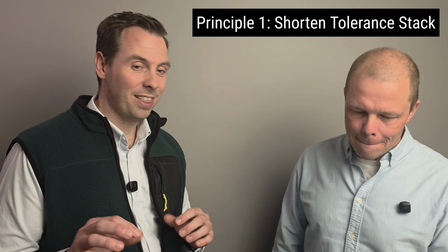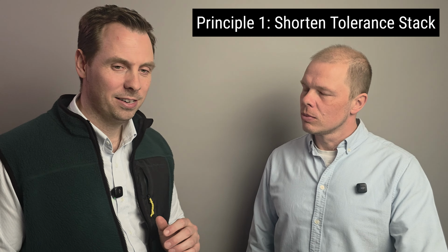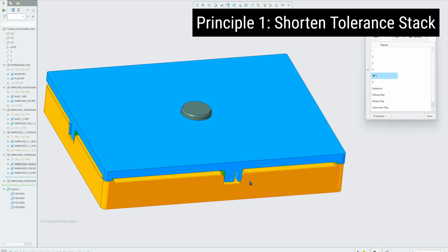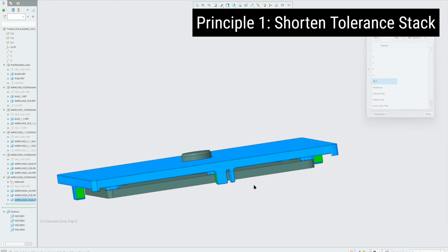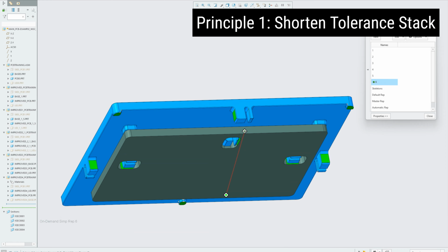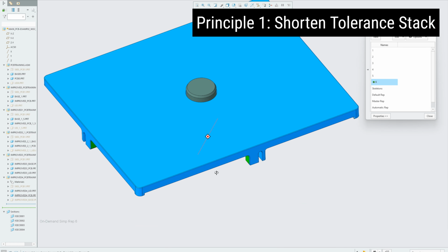There was also this principle number 1 where we could short circuit the tolerance stacks and say if we can eliminate any parts, let's do that. We're not allowed to apply this in this case. Would have made this video way too short. Exactly. So here you see that example where we hide the base, then we are seeing that the PCB is mounted directly onto the copper.